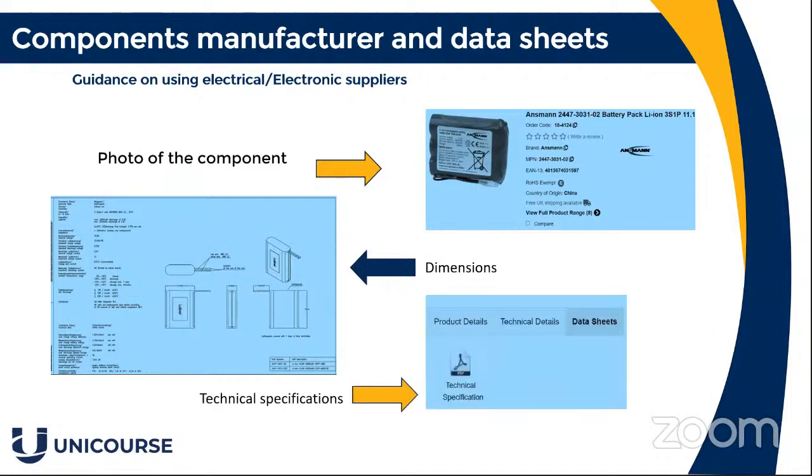Technical specification is also important, and that is something you'll need to know because, for example, you can get one of these batteries, but the current rating is quite low. If it's for a drone, it's going to have a motor inside it, and it's going to be lifted off the ground. It will have to go for so long, so it's important that the current rating is spot on besides the actual voltage. It could be a 12-volt one, but have a very low amperage on it. So it's important that you get the right one for the job. These are things that are very, very important.